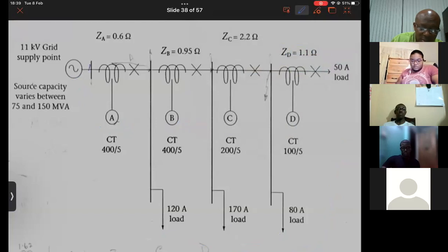The bus bar represents where the relay really is located, but we can't draw it inside the bus bar, so we show it immediately in front. If there was a fault right at the bus bar, right in front of the relay, the only reactance between the source and the relay would have been the transformers, which is why we just did that.